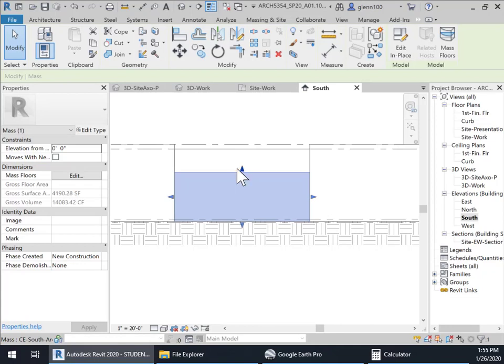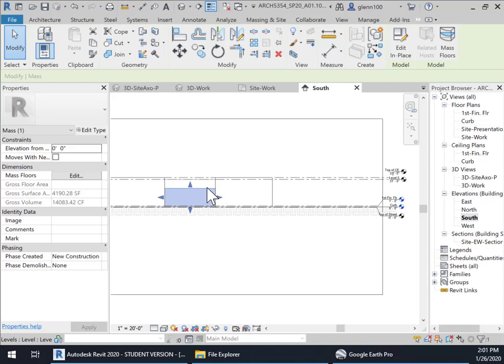There's a variety of ways to do this. The top of this, once again, I'm going to go offline real quick and get those dimensions from Google. So I went offline and got the dimensions of this. This is 15 feet. The facade of it is 15 feet up, and then the back slope dimension I got as 23 feet, I think. Yeah, 23 feet in height, okay? That probably could be calculated to a slope of some kind and then go with the slope instead, but I'm just going to use those two dimensions.